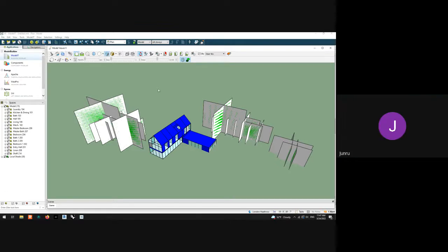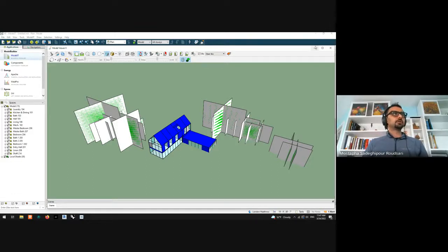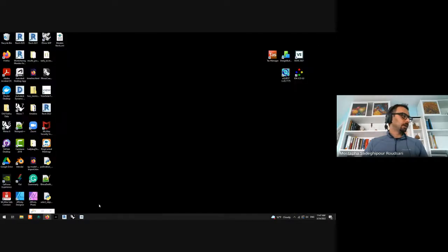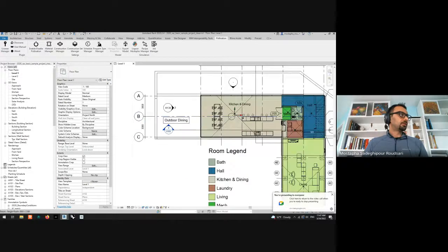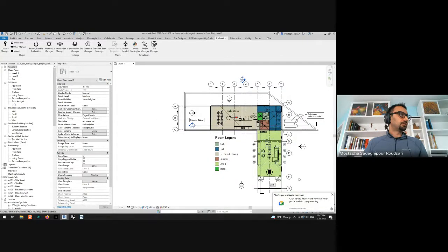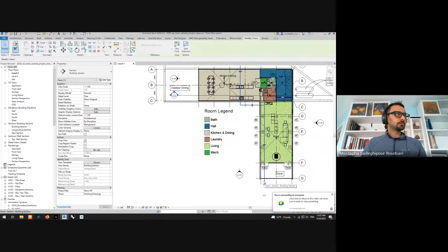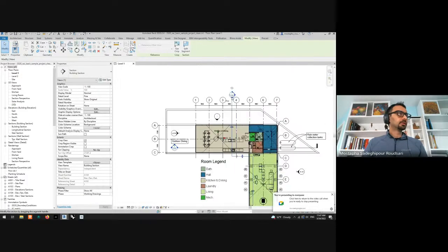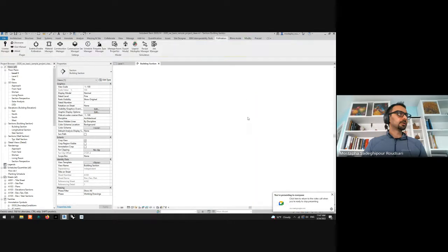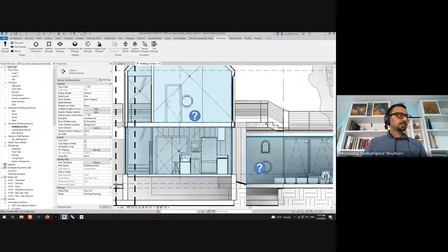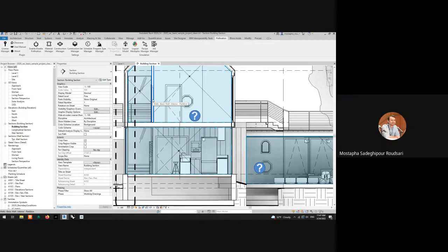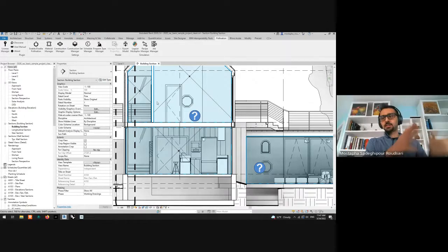I have a question, sorry, maybe I missed it. What happens to the gap between the floors? Oh, okay. Good question, and I'll show it. That's a good place for me to go to the Revit Advanced model. Let me find a section here. Here's a section, go to view. Because these elements are room bounding, your room is not going to go all the way up. And if you do the detailed export, this is how it will be exported.